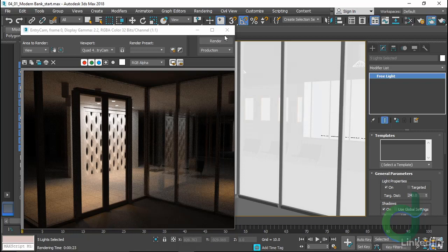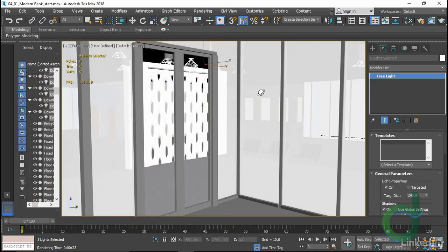Remember that your lighting is an artistic choice. We can light with our photometrics or with spots and really bring that scene to life, and doing it with lots of little lights to really add some play in the space is worth it. We want to light this space to evoke a certain mood, to show off the architecture, and a little tweak here and there is worth it. And also, save time where you can. If your lights need to be just below the fixture so we're not dealing with shadow casting through all the fixture, go for it. Nobody's going to know the difference, and you'll get that wall wash with a lot less render time.